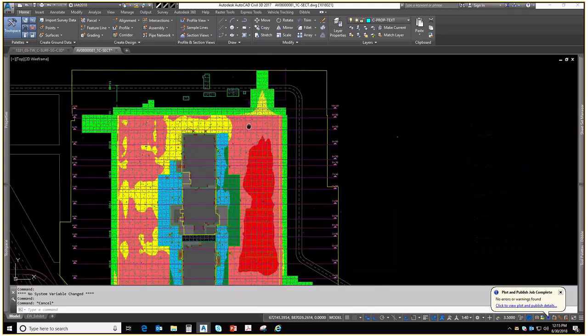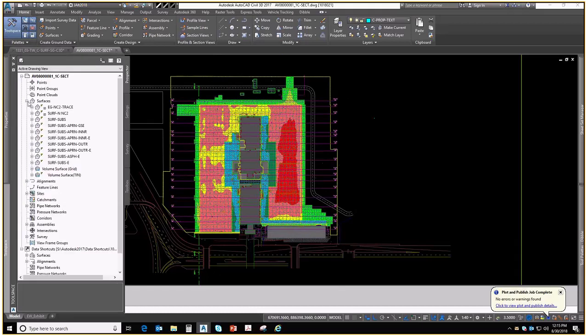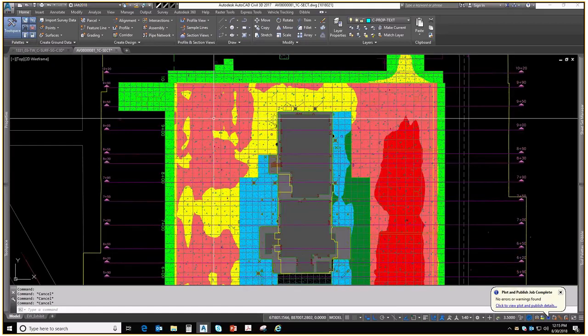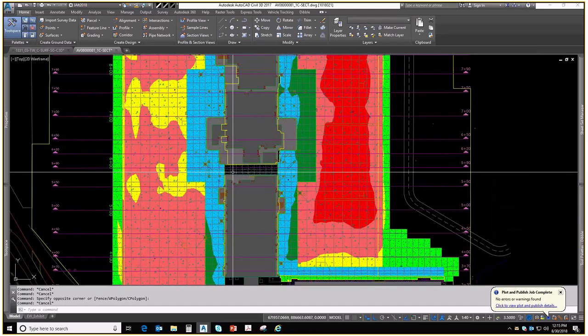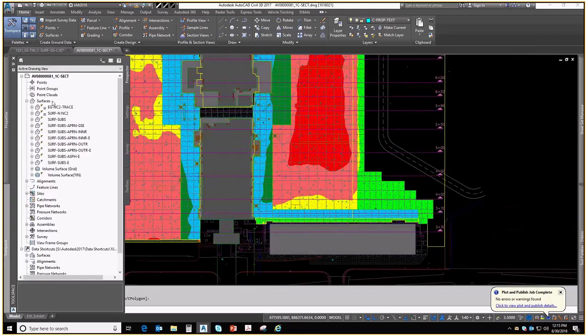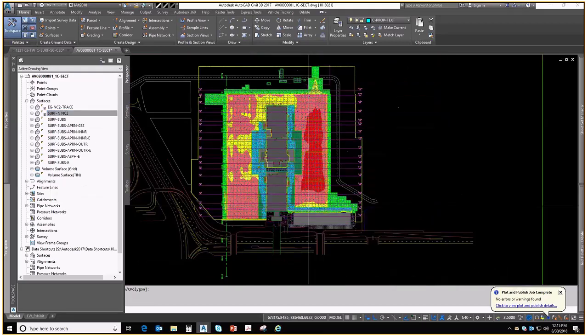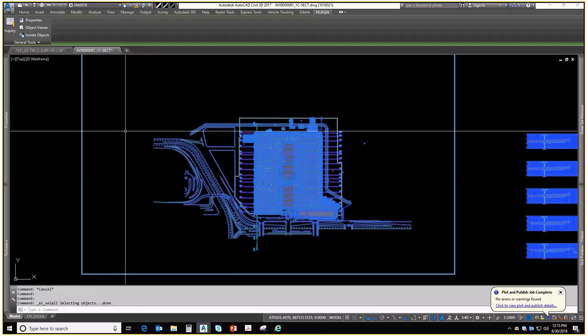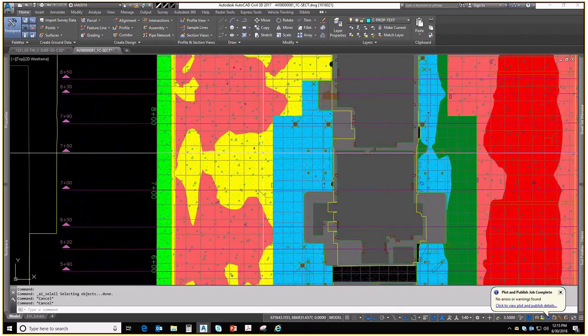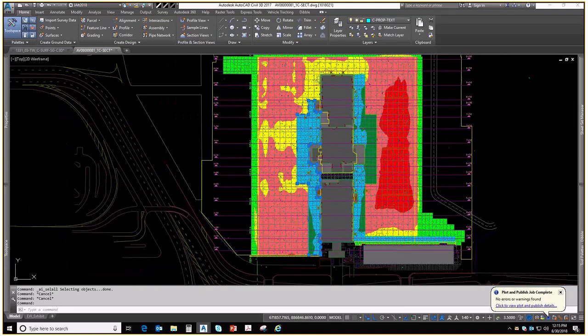So you would have your existing surface, or any kind of surface. You would then create your outermost boundary to hide it. Then you have your... I guess the best way to show you would be to actually do it. So let me go ahead and create the boundary for the existing. Do a new proposal. If anybody's wondering, this is the North Concourse at Terminal 3 at Sky Harbor. We did a project to remove and replace all of the pavement and regrade the apron, and the concourse is in the middle, so obviously it's staying, and so no earthwork in the building.